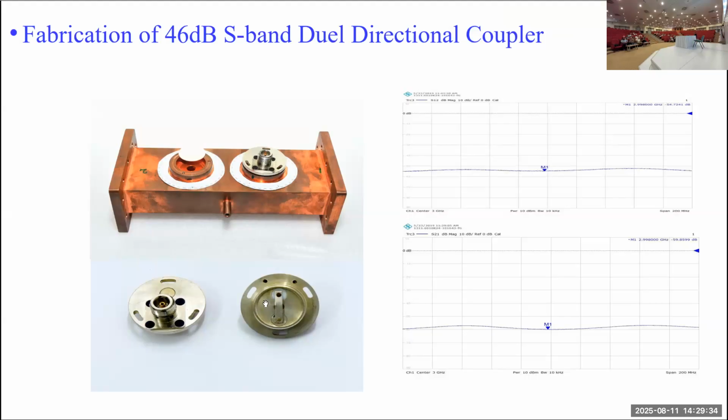But here you want to measure how much power is coupled to the system. You need very small coupling. You must know the coupling of your antenna. Efficiency is not required here, because we are not coupling RF power to the structure. We are just testing how much power is coupling. For example, if you have a big bowl of rice, you can test 2 or 3 grains to test the taste.